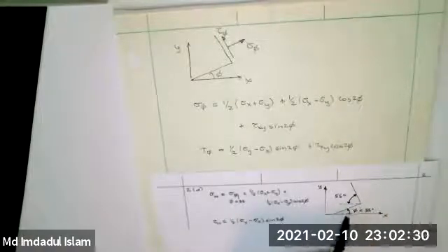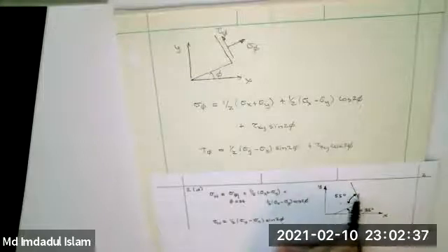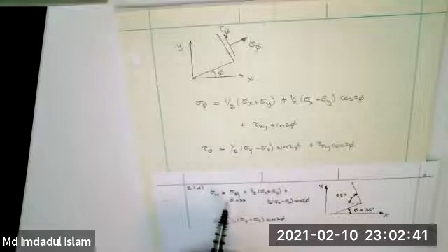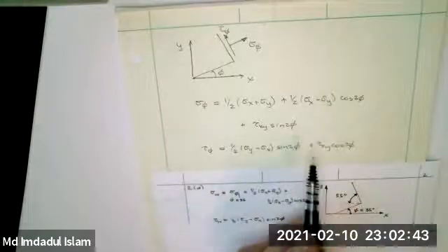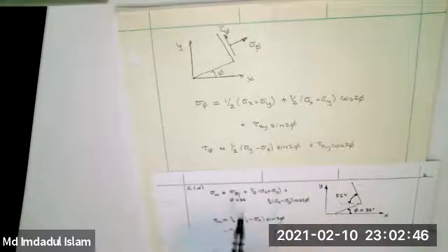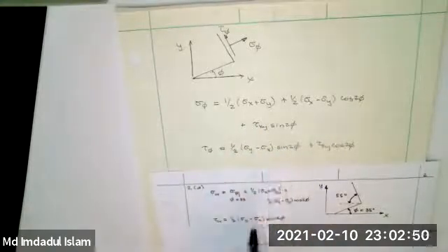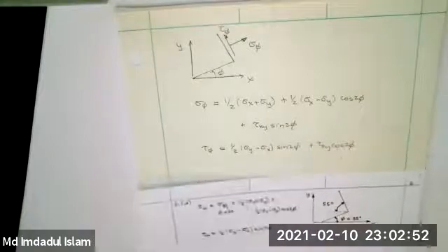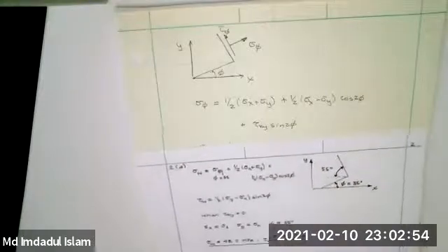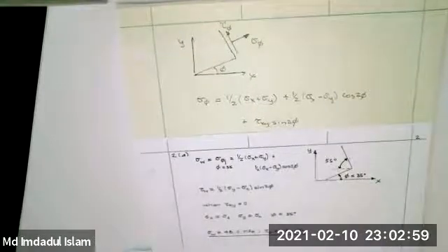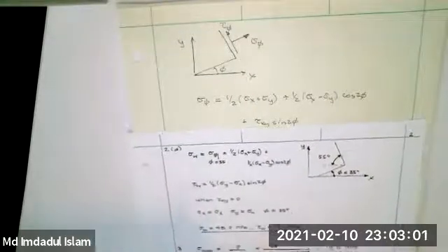And so you take the 90 degrees here. This is 35, 35. So phi is 35. There is no shear stress. This is a hoop. This is a pressure vessel, so this tau xy term is 0. And so these two terms are the first two here. And this is the first term here. And then you can calculate it as it's done. And in particular, what you'd be interested in is the stress across the weld.